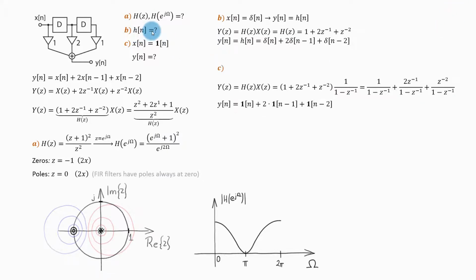Now the impulse response. So again, to get the impulse response, I need to feed the Dirac delta pulse into my system, and when I do, the z image of the output will be equal to the transfer function, which in this case has this form. Now I need to take the inverse z transform of this to get the impulse response in the time domain, and that is very easy.